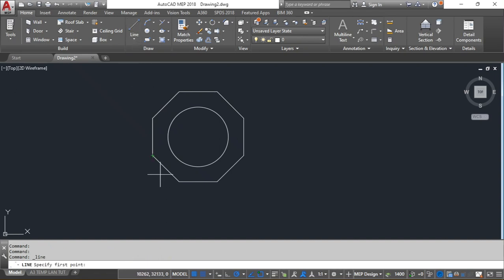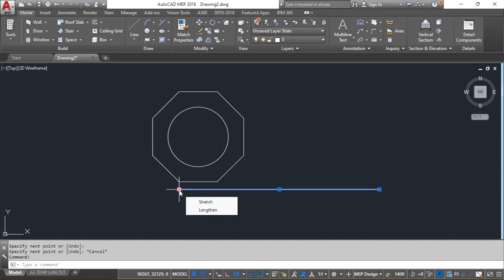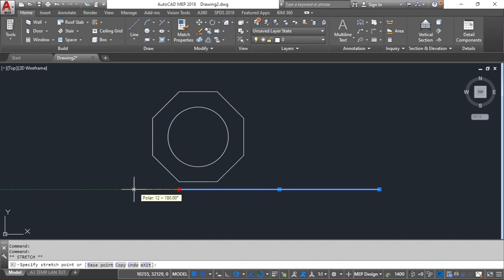So pick the line, choose an endpoint. As I'm going downwards, I just type 2. Around here, I'll draw a line of an arbitrary distance. Let it just stop there. Click this and extend it to some reasonable length. Hit escape. Now we need the other axis.